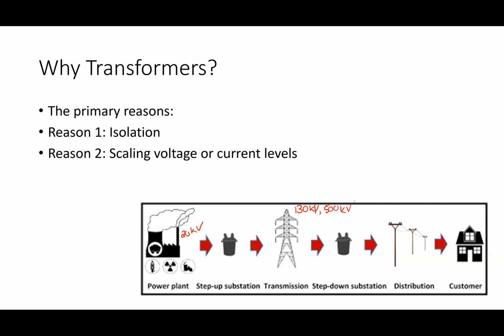All right, now, there must be a good reason to do that. What is it? Lose voltage in distance. Smaller amounts of current will flow if I step the voltages up really high, okay? And if I have a lot of current, what's the problem with having a lot of current? I'll have a lot of I squared times R in all the resistors. There'll be a lot of power loss, all right? In other words, the Duke wants the power that leaves that power plant to make it to your house, because anything that doesn't make it to your house, they pay for and you don't. They still charge you for it somehow, but they would reduce their operating costs if they did, right?